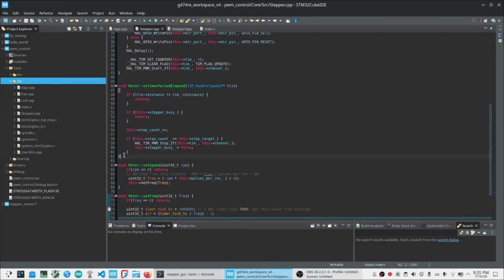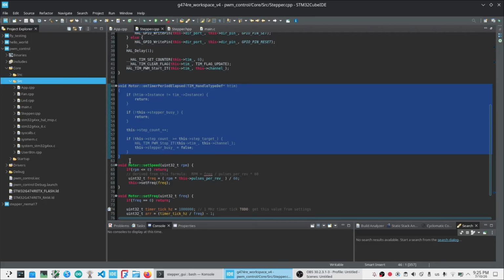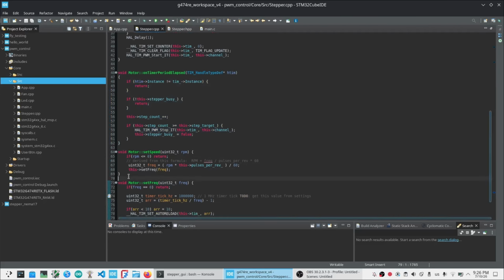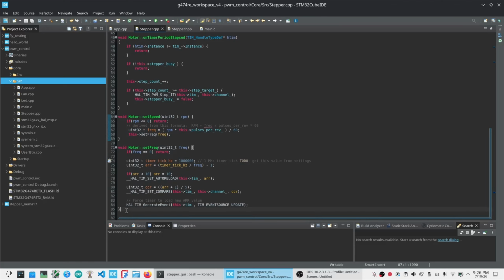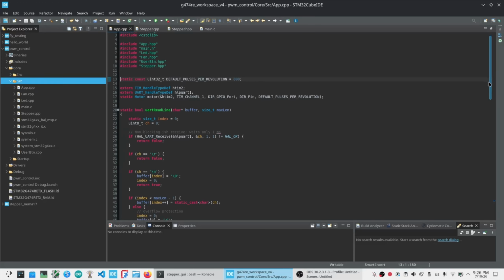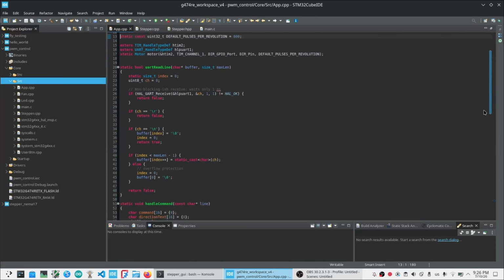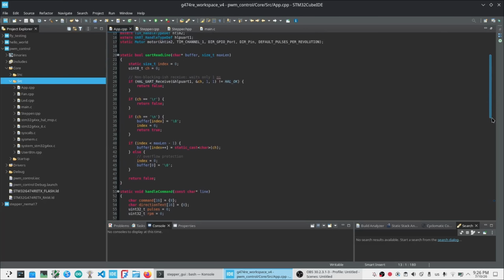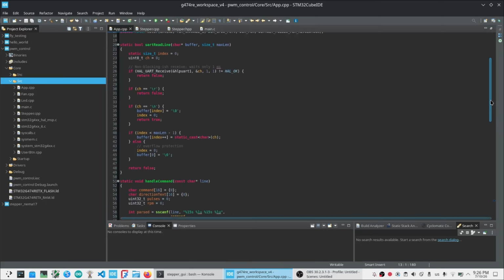One important lesson from this project is that hardware timers are necessary for accurate motor control. At first, it is tempting to create pulses manually using delays, but this is not precise enough. Using the STM32 timer gives stable frequency, accurate pulse generation, and better control. Another important lesson is initialization order. In embedded C++, we must be careful with global objects. The timer and peripherals must be initialized by CubeMX generated code before we configure them in our own classes.